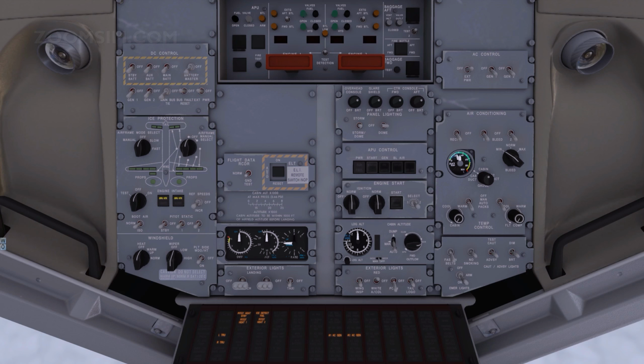The airframe mode selector has 4 positions: off, slow, fast, and manual. In the off position, the automatic boot sequencer is off. In the slow position, automatic sequencing of de-ice boots uses a 3-minute cycle. In the fast position, automatic sequencing of de-ice boots uses a 1-minute cycle. In the manual position, dual distributor valves, or DDV, and heated check valve heaters are activated manually. Only the off and fast positions are currently implemented.